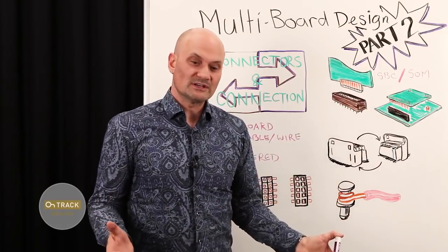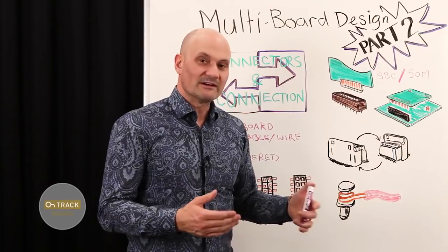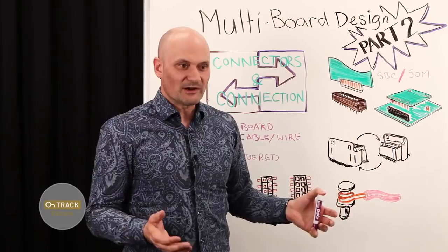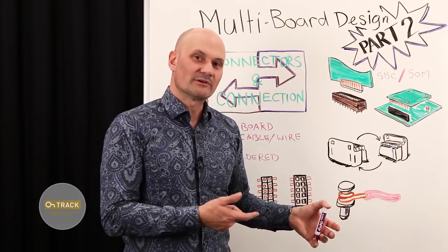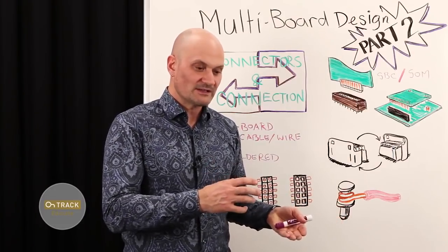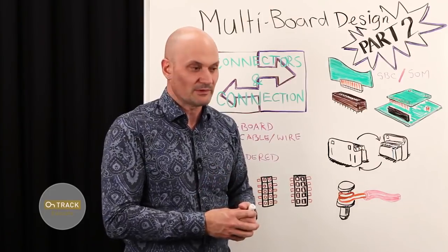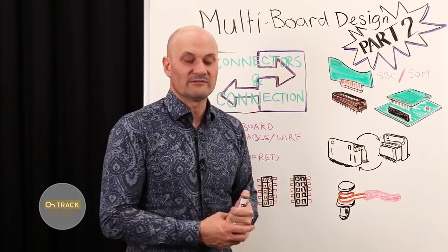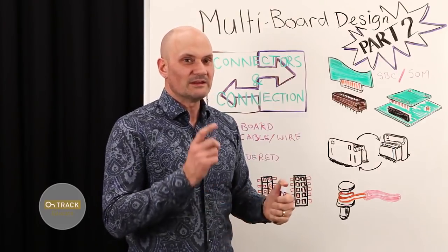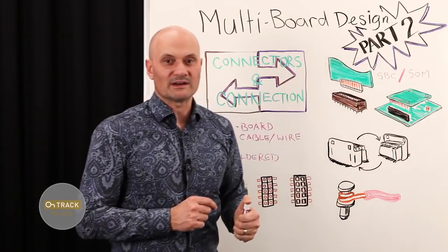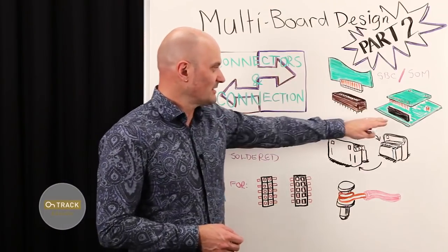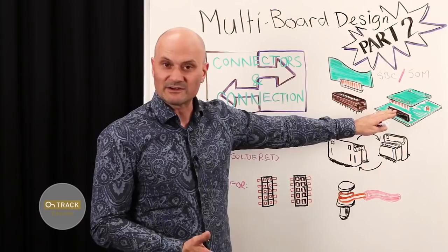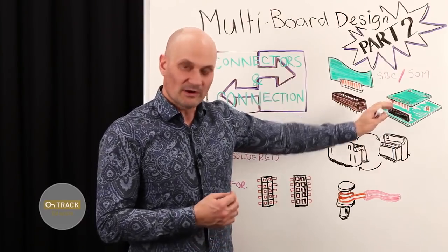If you're going to ship heavy currents, if you're going to connect, is a better word, power supply, power and ground through a connector from a baseboard to a daughterboard, for example, and that daughterboard needs a reasonable amount of current or power delivered to it, then one of the most important characteristics of the connector is its current handling capacity, and that's usually specified by the manufacturer in amps per pin.